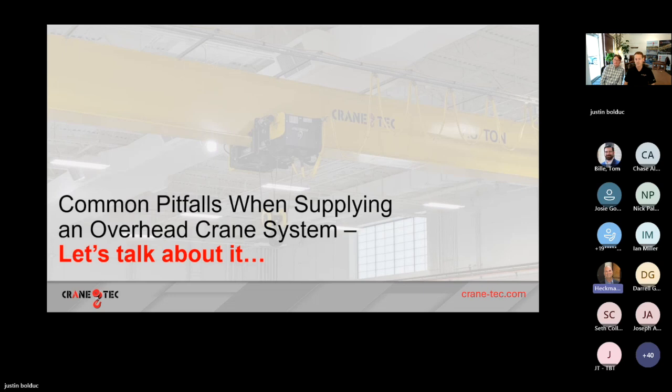We're not going to get into the rail business. We can provide the rail as a metal building manufacturer, but I always look at it from a practical standpoint. We give you the beam, Mr. Contractor, and then the rail is provided along with the crane system itself, and the end stop that sits on top of that rail is going to be provided by the crane system provider.